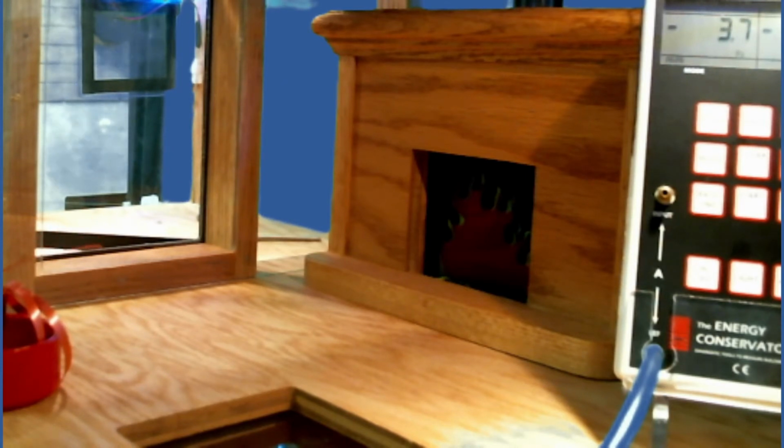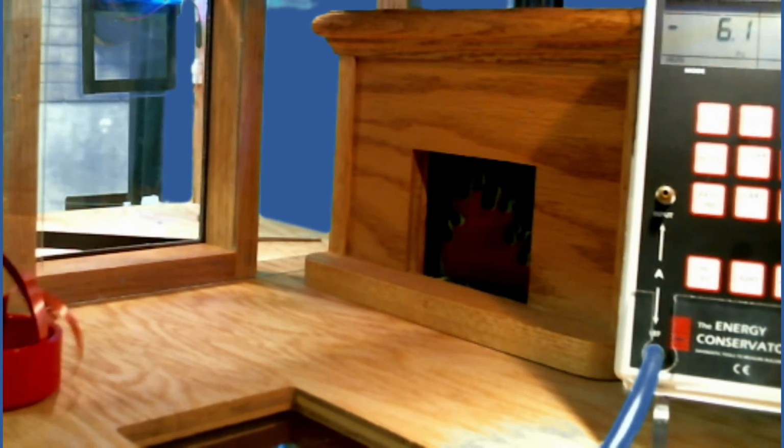Air handler fan is off, and we're down to somewhere around 3. And then when we turn the air handler fan on, it didn't quite double, but it was pretty close to double. So now we may or may not have leaks. I know that I've got leaks in my house here, but when you get a change like that when the air handler comes on, it could be from door closure or it could be from duct leakage. In this case, I know I've got the bedroom door over here closed already.